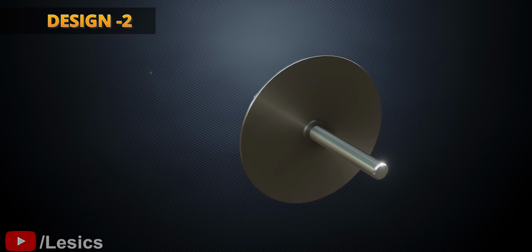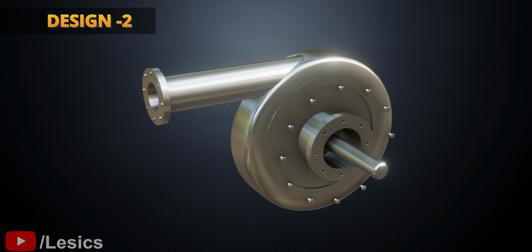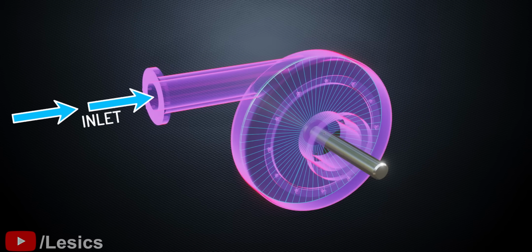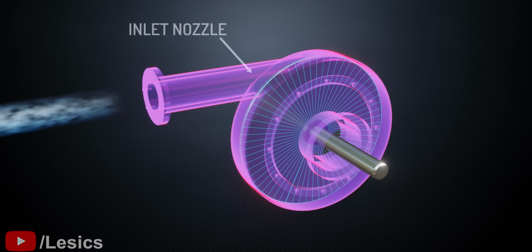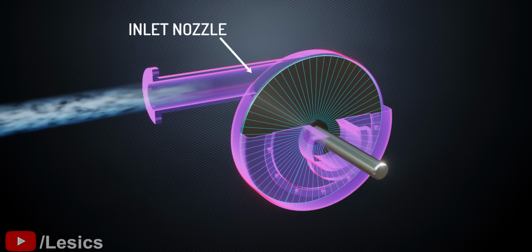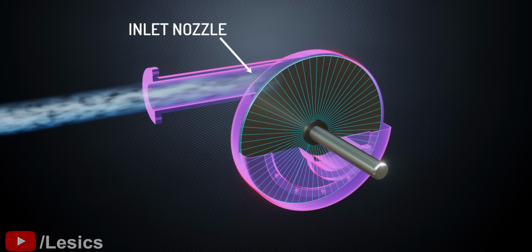Let's place this shaft disk pair inside a casing. Now the fluid enters through the outer casing, tangential to it. A provision for the fluid to exit is at the center of the turbine. Assume an inlet fluid with slightly higher pressure than the atmospheric pressure is entering the inlet nozzle at low speed. What do you think about the path this fluid takes?